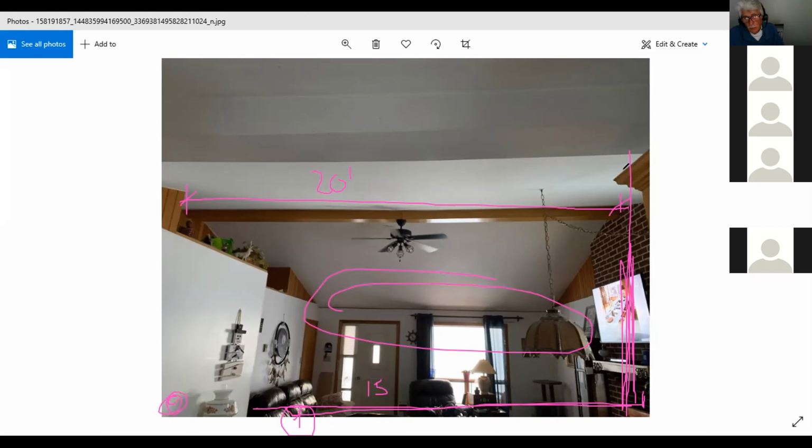Do you follow what I'm saying? Yeah. So like I said, you go measure from there to there, okay? And then go in the basement, or wherever the ground floor is, and measure from this wall where the columns are. And then in plan view, see if this beam happens to correspond to where the beam is underneath the floor. It most likely is, you understand?